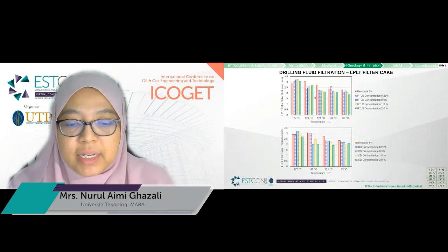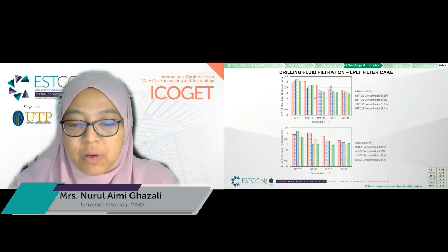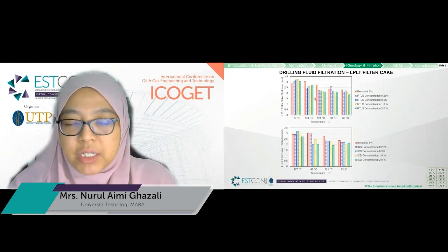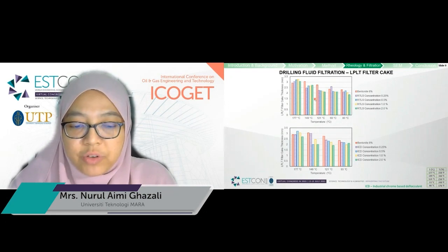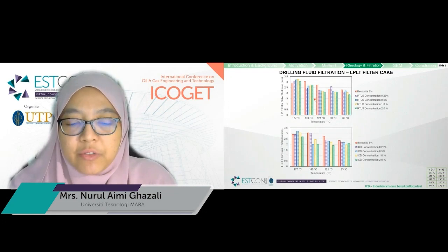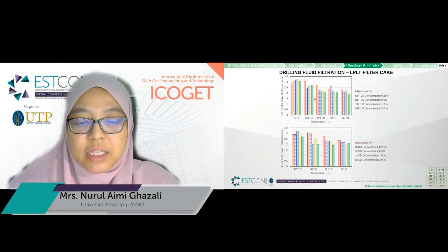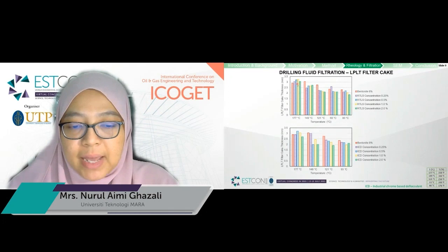As mentioned earlier, the flocculant is able to reduce the fluid loss as a secondary function in drilling fluid. When the temperature increases, the fluid loss will increase due to reduction in viscosity of the filtrate. At high temperature, the fluid additive is also prone to degradation, but slight changes show that the additive still works.